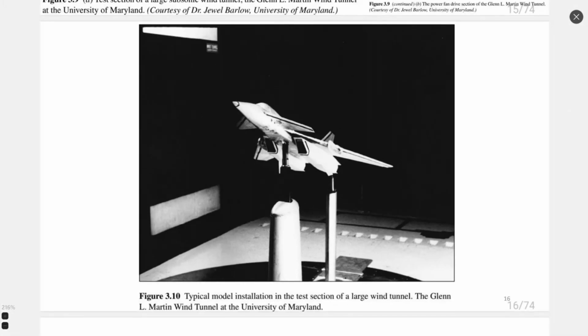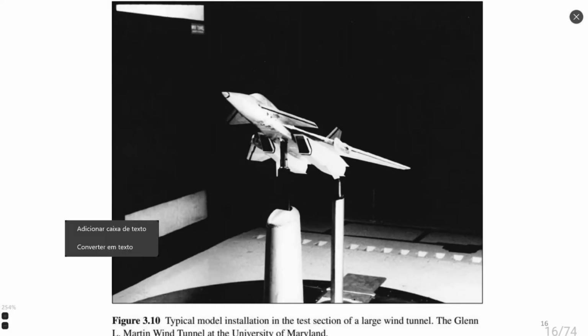Here is just an airplane model to test inside a wind tunnel. What is the advantage of a big wind tunnel? That is, you can put a bigger scale airplane with many details. You can install several sensors and make good quality measurements, because in such a case, the geometry can be produced with very good quality.